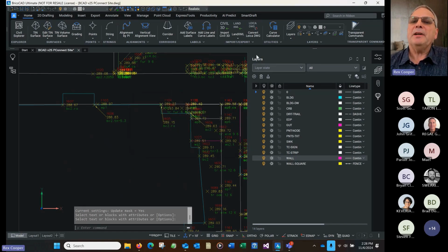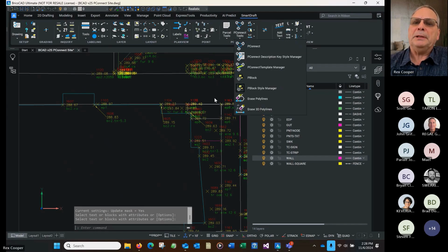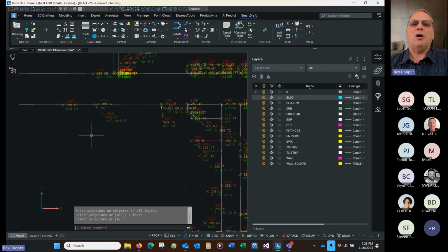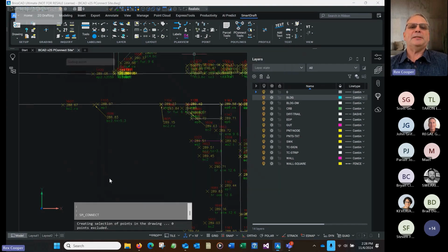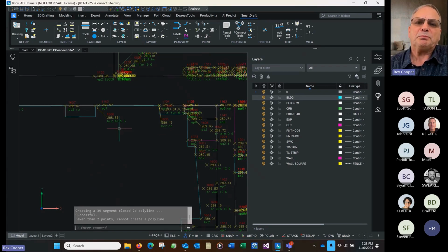And now it's a negative, and here's where I just go over here into the point P-connect commands, erase just the building layer. So all the building layer has been deleted. Go back into P-connect, and then just this time pick building, because that's all I want to rerun, and process. And it's fixed that quick. It's an easy way to fix if there was just a small little error in a right or left when someone's entering in a code.